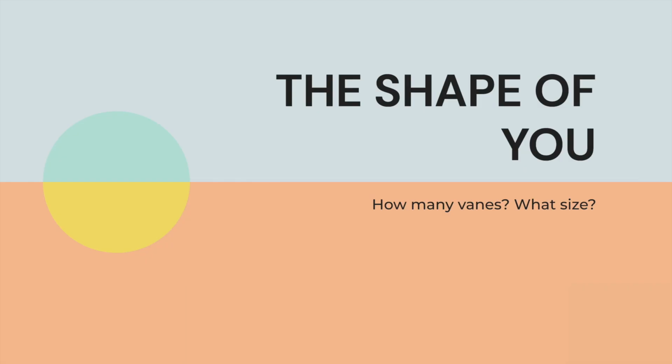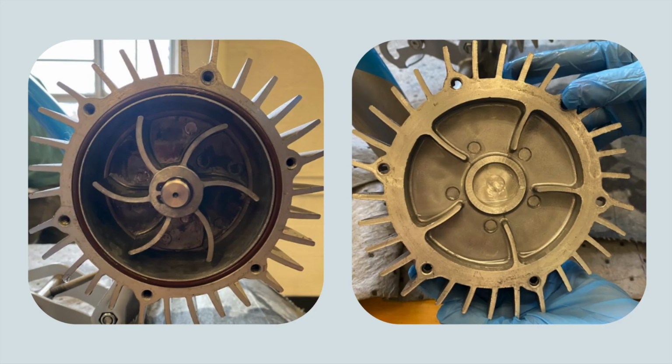This explains why the bike experiences resistance at higher speeds, simulating the real-life conditions that a bike rider would experience on a road. The impeller has 6 vanes that do work on the fluid, while the casing cap has 5. Cap vanes also oppose the direction of the impeller vanes, which facilitates the fluid being transferred back to the impeller. The impeller vanes are much wider than the cap vanes because they are generating the angular momentum in the fluid as the impeller spins and can move the fluid easier with a greater surface area. Since the vanes on the cap act to transfer momentum back to the impeller, they do not need to be as wide or as numerous as the impeller vanes. If there were more or wider vanes on the cap, the resistance generated would be much thicker than what is targeted by the system to simulate road conditions.